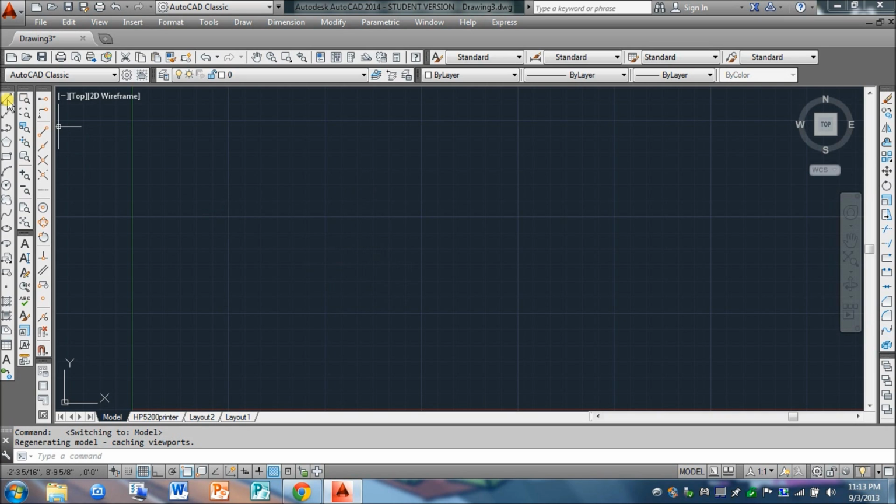The way you do that, the easy way, is to simply draw a line. Since it has to be exact, you should press function 8 and it'll give you a straight line across. So we're done. Just hit enter to get out of the line command. The next thing we have to do is start building up the first shape. And I'll be starting on this side.